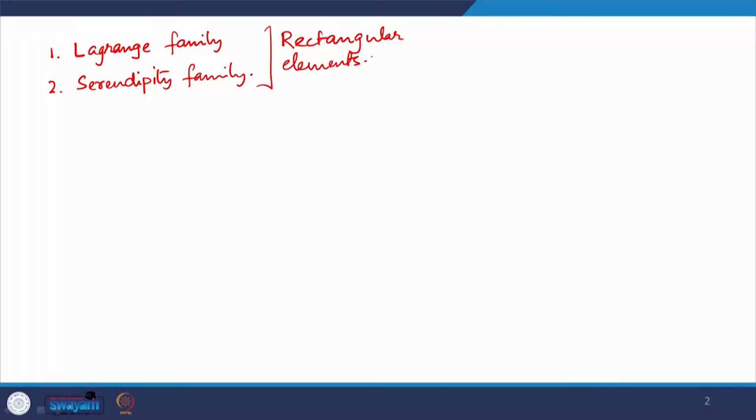So, I take the Lagrangian interpolation along x, I multiply it with the Lagrangian interpolation of desired degree along y direction, and then normalize it with respect to whatever node we are looking at, and we have the desired interpolation function, very straightforward. And that way we can generate any degree of polynomial, any higher degree elements do not really pose much of a challenge.